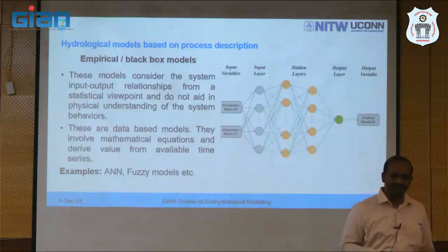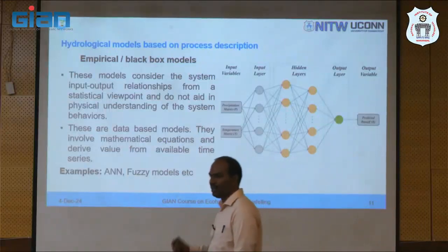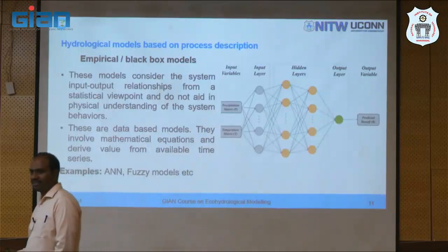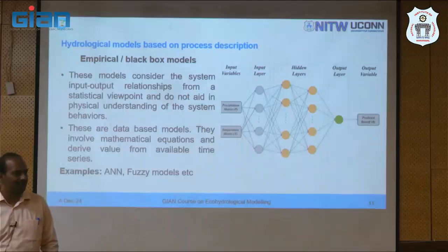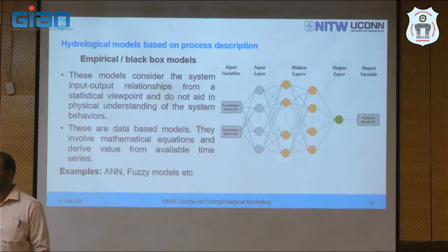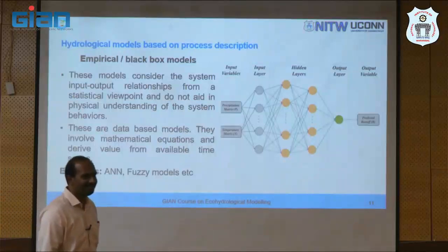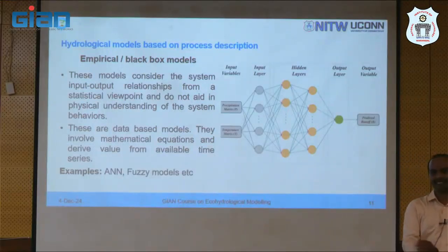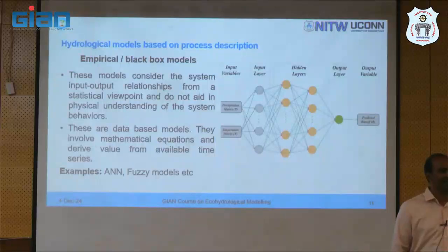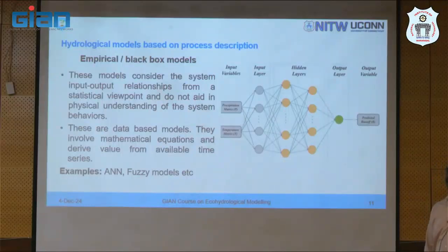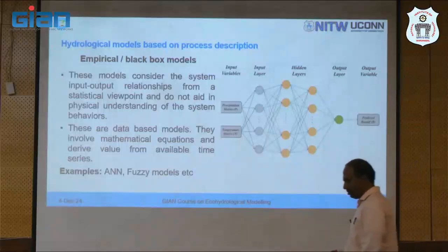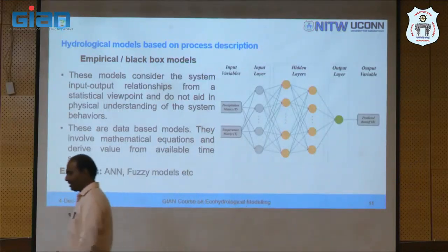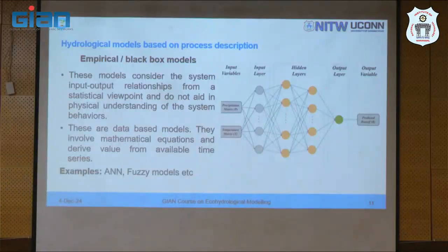And we have our understanding that some part of that goes to runoff. So, a fraction of that, what we call the runoff coefficient. Now, how is it empirical? Yes, Q is equal to CIA. Since it is CIA, units are not matching, it is empirical. Huh? Units will match. There is a factor that needs to be changed, right? Depending upon the process, it's good that we have done this exercise to classify them into different models.